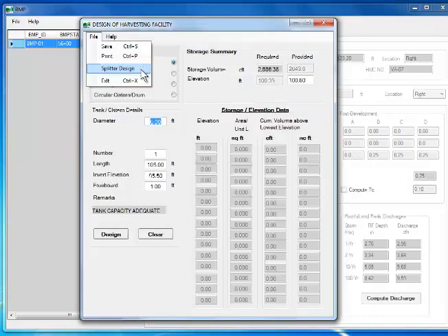There are situations where the rainwater harvesting facility is designed as an offline facility, where the water quality discharge is directed to secondary practices like rooftop disconnection, vegetated filter strip, grass channel, infiltration and micro-infiltration, microbial-retention, stormwater planter, dry swale and underground infiltration soak-away pit.